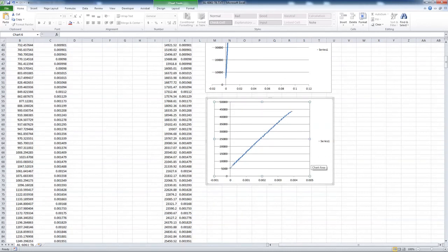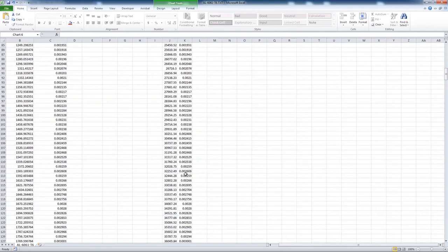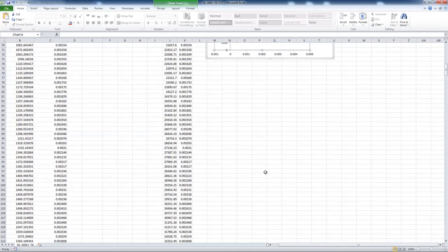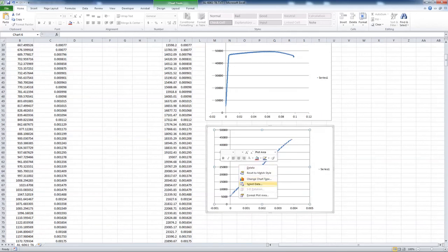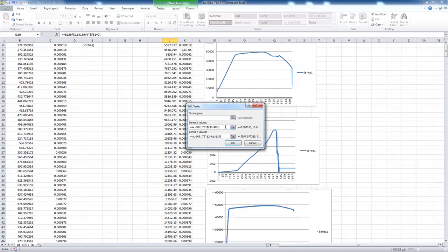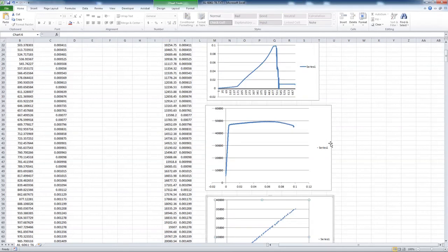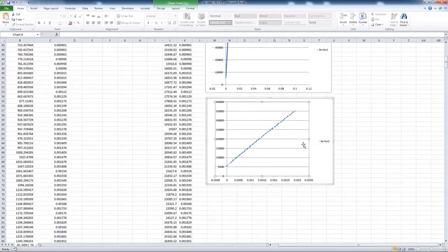Still have a little bit of curvy in there. It probably wouldn't hurt if I took it down to maybe 35 KSI. So let's do that. There should be enough data points to get a linear regression line off of that. So maybe 123. Some of these materials, they just keep looking a little curvy. You kind of have to go with it. Now we do have an advantage that we know what the modulus of elasticity of aluminum ought to be. And I think we'll end up getting pretty close to it.